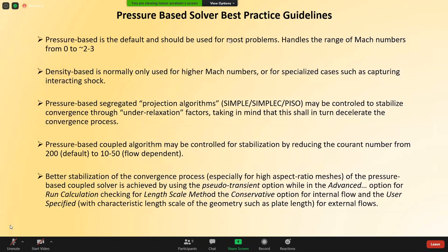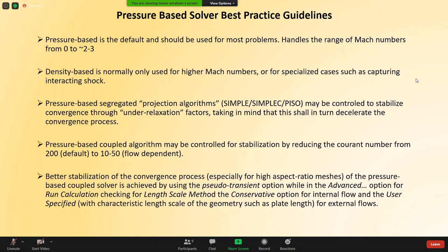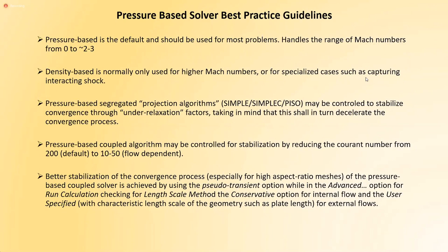Pressure-based solver, as I said, you can use them. Traditionally, it was for incompressible flows, but you can use them to 2 to 3 Machs. Density-based solver normally used only for higher Mach numbers and for capturing and interacting shock. But again, writing such a sentence is very funny. I mean, like boundary layer shock interaction is a problem which is not quite solved yet.